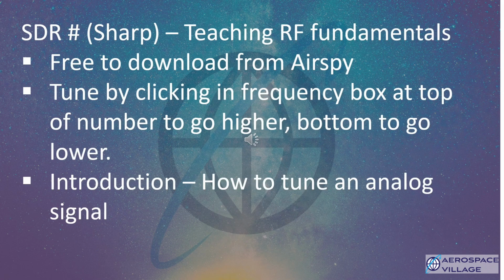You're going to be using the SDR Sharp program. It's free. You plug in your SDR into the USB port, start up SDR Sharp, push the play button at the upper left, and you can start listening to radio signals and analyzing them immediately.